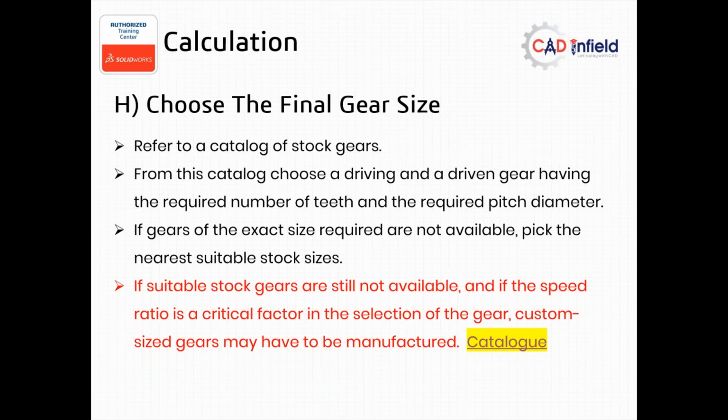Later we'll have a stress calculation. In machine design, whatever you learn is directly the stress or strength calculation, but the majority of the time, the designer will not do any strength or stress calculation over the catalog itself. If your company is the direct vendor where the gear is manufactured, they will give you another internal catalog. Once you select that gear, it will say this particular gear will have a stress value up to this, we have considered the yield strength up to this, and it will be useful up to this deformation. All those things are mentioned in the catalog.